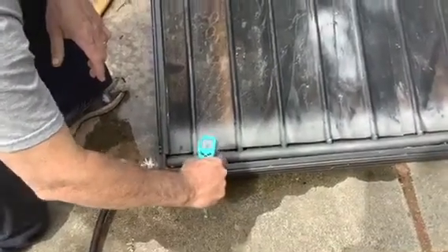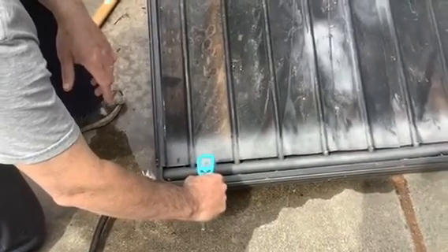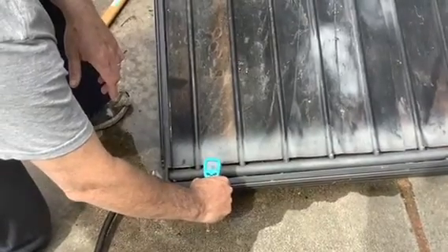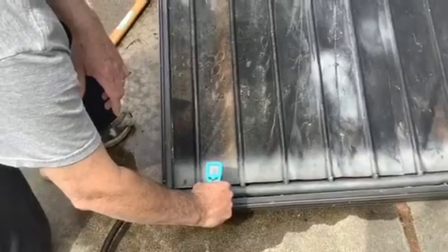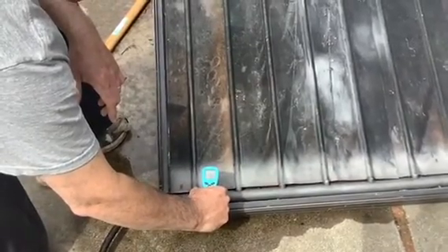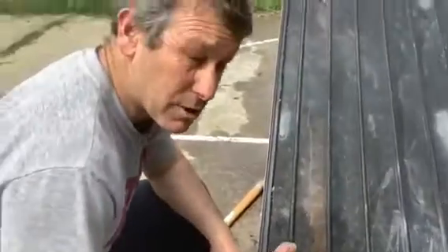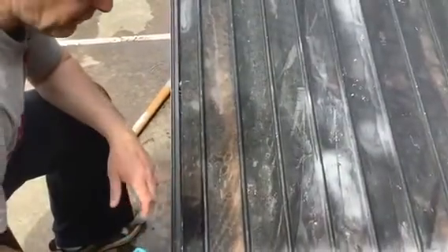I'm using this right here, and this is taking the temperature of the manifold pipe. It's like 85-ish. That outer edge is about 80, but about 85-ish. If I move up, now I'm pointing at the fin itself, and I've got 93, so that looks pretty good. This should be able to warm up water somewhat, but not great. On a really sunny day, this surface up here could get to 140.